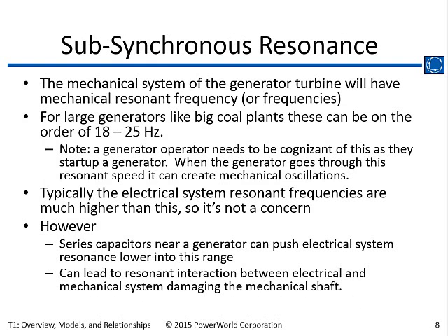There's something called subsynchronous resonance, which can be an issue when you're doing wind turbine and wind farm modeling. It also occurs in other aspects of the grid. These are oscillations that occur on the order of maybe 15 to 30 hertz in the system. Subsynchronous resonance is something that transient stability does not address either, because of the model time frames.